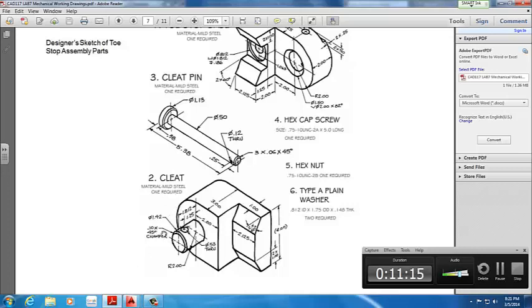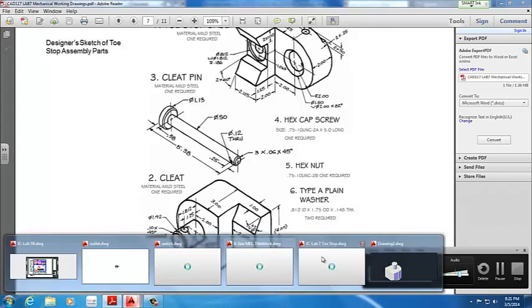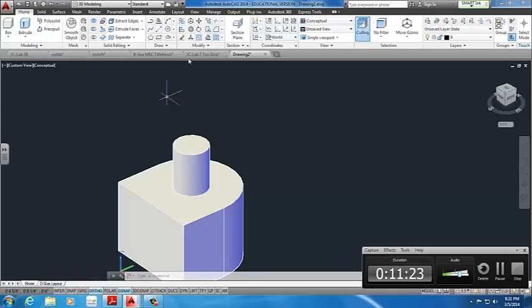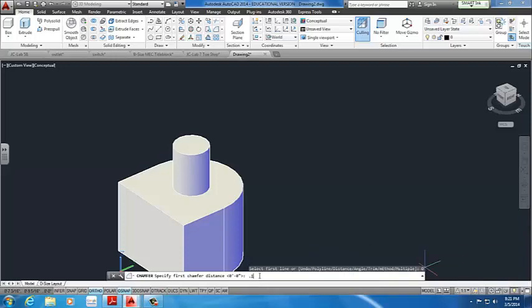So what we're going to do instead, we're going to use chamfer, as it specifies right here. To do that, we go back to the drawing. We go to chamfer command, which is going to be right there where fillet is. Go to chamfer, and it's going to ask us for a few different options. So our basic distance is, either we can type in, distance 0.1. Why is this still here? So 0.1, enter, and 0.1, enter. For both distances, that gives us a 45 degree.